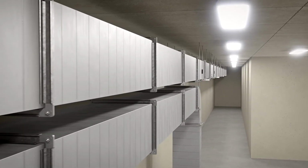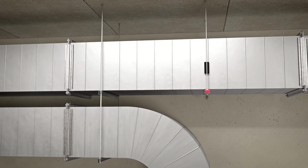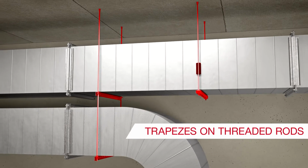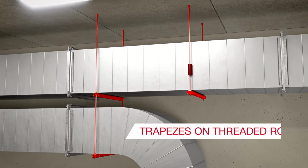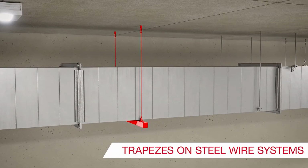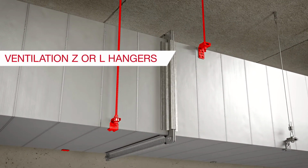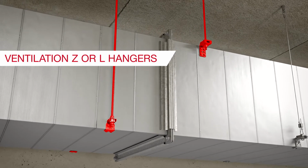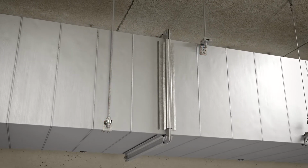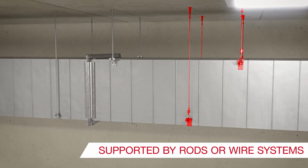The third phase commonly consists of backbone rectangular ducts. Frequently used solutions for this phase include trapezes on threaded rods, with various channels in between them to support the ducts. Trapezes on steel wire systems are another widespread solution. In some areas, ventilation Z or L hangers with self-tapping screws are often preferred. They can be equally supported by rods or wire systems.